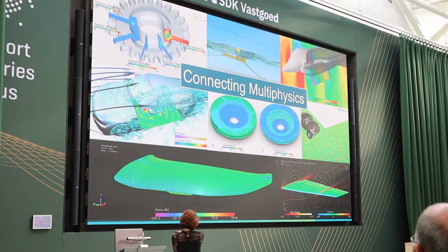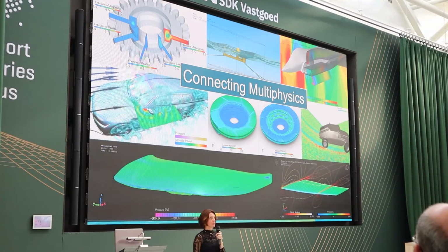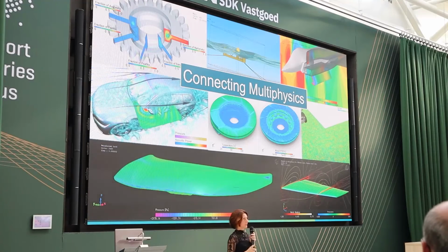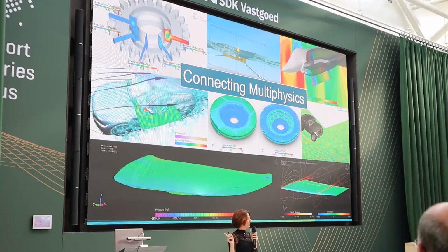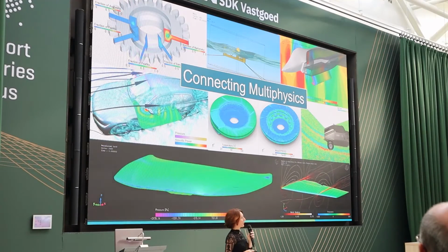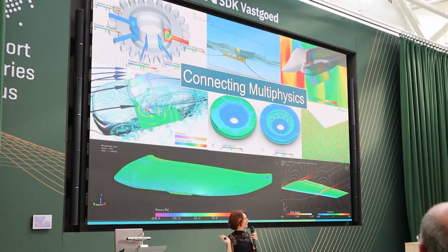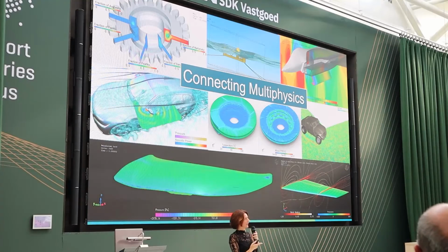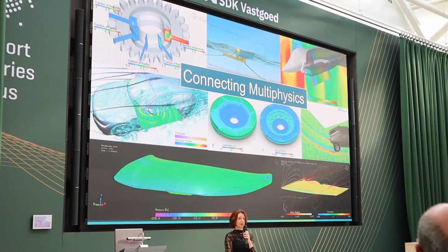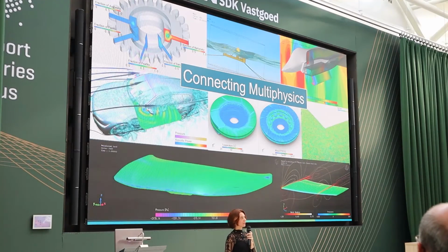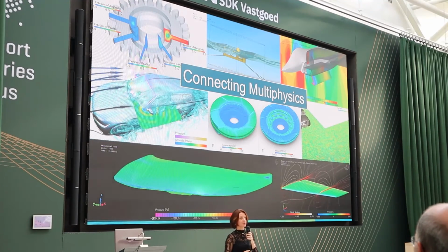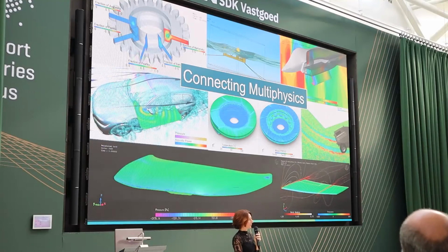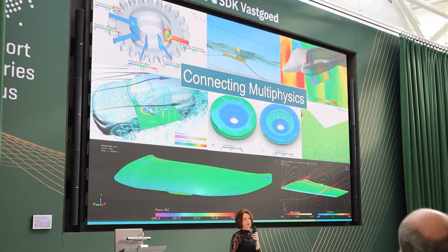There is something that I like to show here: the fluttering of the wing. I think everyone knows that we need to be very accurate, and everyone is trying to do some very nice aeroelasticity. But there is one point that we never speak about: it's exactly the same in the automotive industry. Up to now, the OEMs are not running this simulation because it's too complex and takes too much time, and they have to wait for the car to go to the wind tunnel aerodynamics test, and then they check if the vibration of the hood is fine or not, and otherwise they have to strangle the hood, which is not very good for fuel consumption. So this is why a multi-physics approach helps you to get some answers before going to the production line.